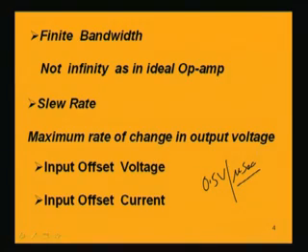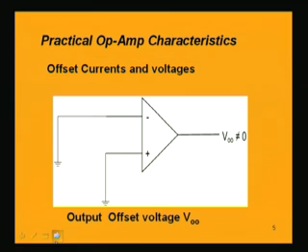If the transistors in the differential amplifier are perfectly matching, that means the same collector current, same base current, and the resistances which are connected are also exactly the same, then the offset voltage and current will not appear. This is the DC condition, mind it, coming from the DC condition of the differential op-amp. So, let us again see an op-amp circuit.